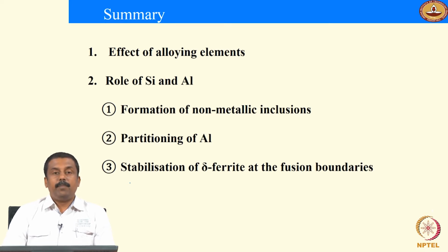And if you form very bulky, large non-metallic inclusions, you would expect the weld metal properties to deteriorate significantly. Therefore it is very important to control the environment, especially the presence of oxygen during welding. If you use GMAW, the use of a proper shielding gas as well as atmosphere protection of the liquid melt is extremely critical in controlling the size and volume fraction of these inclusions.